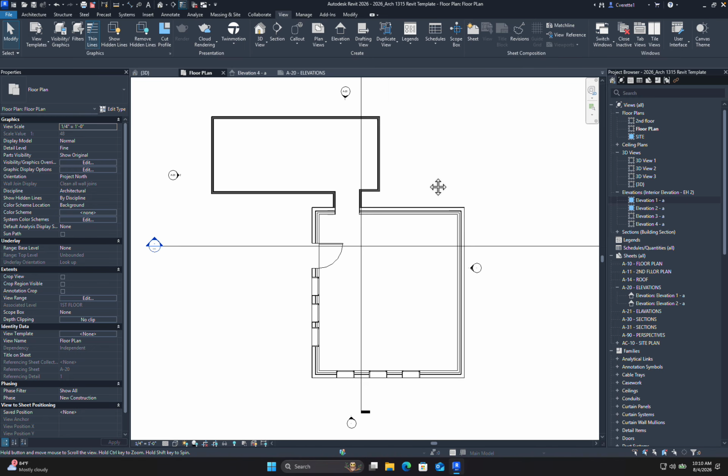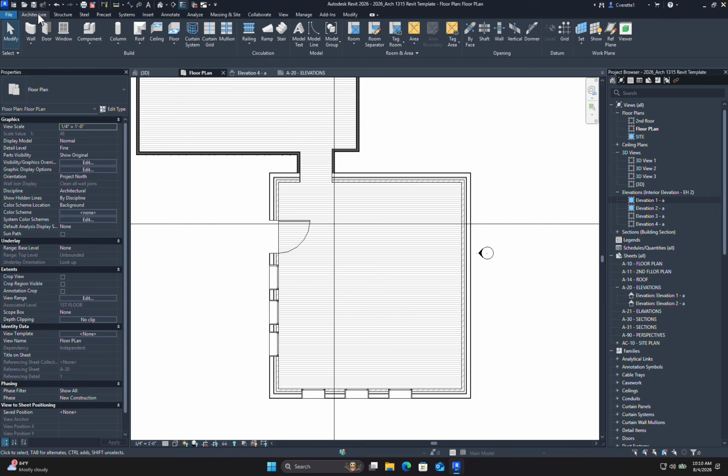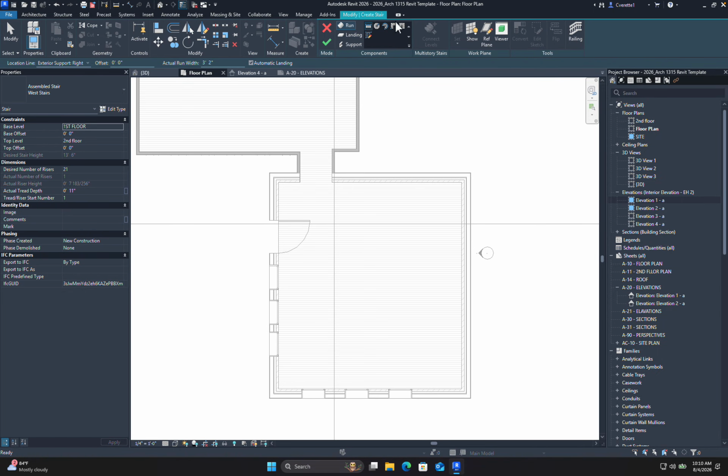All right, what's next? Some stairs. We'll go to the architecture and we'll look for stairs. I mean, don't get me wrong, we got railings, we got mullions, we got curtain grids, whatever those are, right? We got model tests. Oh, stairs, right? And we'll notice that there's one for ramps too. However, stairs, it is a little bit funky. I would say I'd still refrain from the spiral stair, but it's available, right? You could make a very grandiose stair.